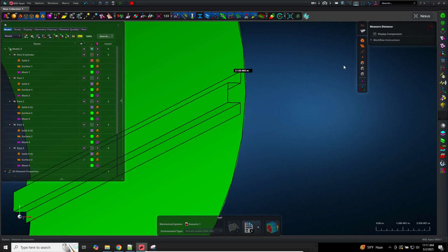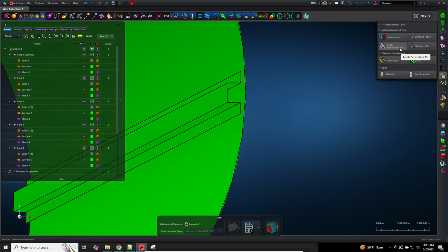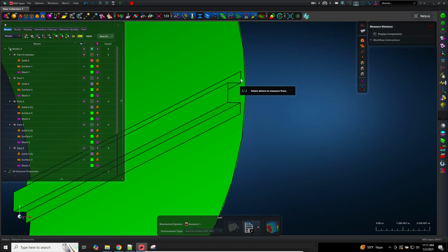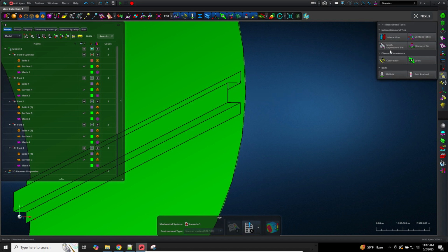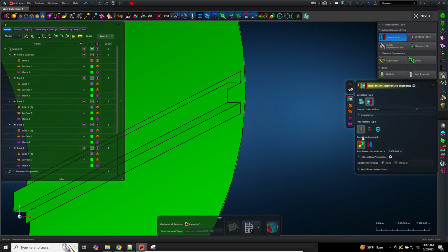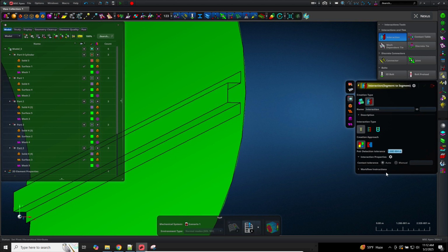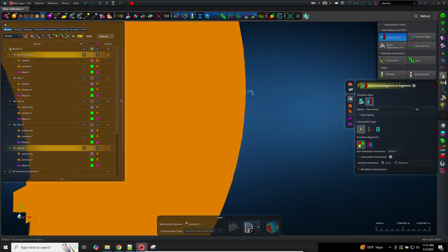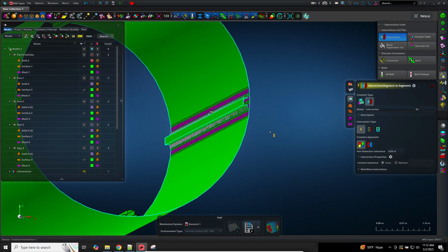So here, when I was going through this exercise, I really like using a contact distance of 0.03. What I did here was I measured the distance. Here it told me it's 0.02, and then I said, you know what, I'll round it up to 0.03. So let's go back here and use that contact distance. 0.03. And we'll go ahead and select that as my contact distance.